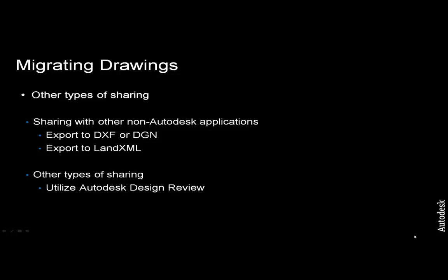Some additional options that are available if you want to share your drawing with non-Autodesk applications are exporting to DXF or DGN files or exporting to LandXML. Many other applications can also read a LandXML file.